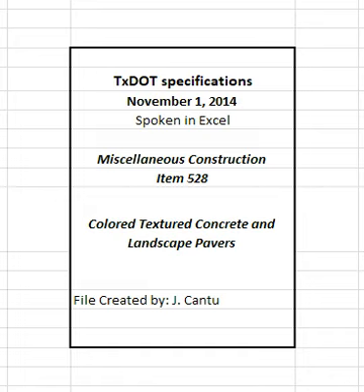Palletize reusable pavers and completely wrap the pavers and pallets with plastic to protect during storage. Safeguard the pavers from theft and/or vandalism while the contract is in progress. Deliver salvageable excess pavers to a stockpile location on the project unless otherwise shown on the plans. Dispose of unsalvageable pavers in accordance with federal, state, and local regulations. Replace any pavers deemed unusable with new materials as necessary and as directed. Remove paver units damaged during compaction and replace with pavers of equivalent size, shape, and color.